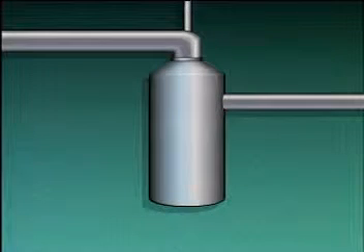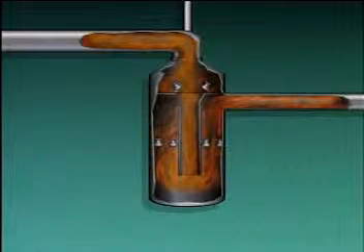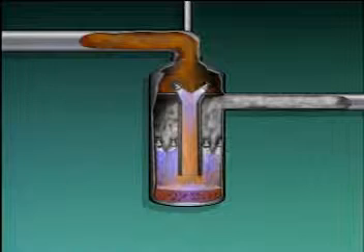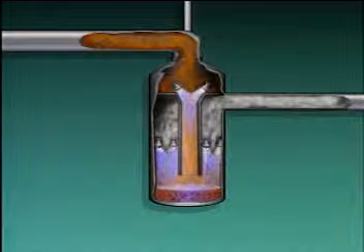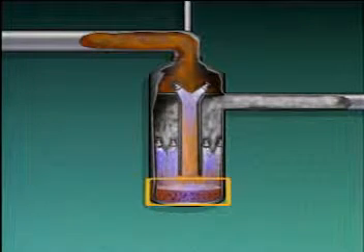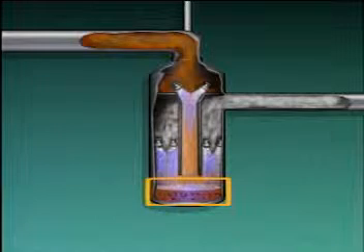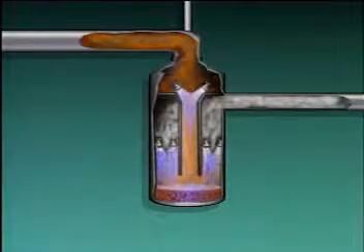Scrubbers can be classified as wet or dry, depending on what they pass the combustion gases through. In a wet scrubber, combustion gases are passed through liquid sprays. Particulates in the combustion gases stick to the liquid and collect in the bottom of the scrubber. The liquid spray also separates sulfur oxides from the combustion gases by absorption. The sulfur oxides are absorbed into the liquid, which falls to the bottom of the scrubber. Both the particulates and the sulfur oxides are removed from the scrubber along with the spent liquid. That's basically how a wet scrubber works.